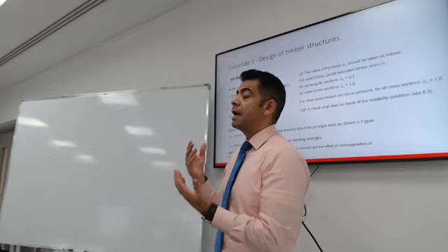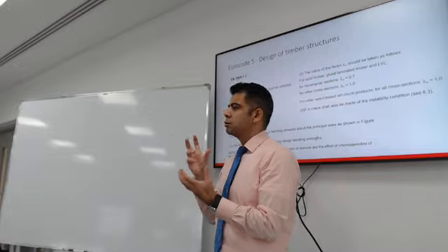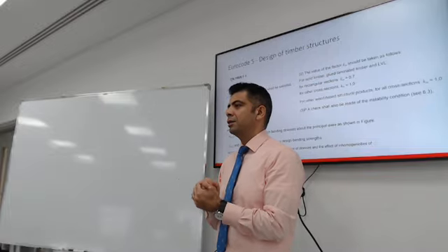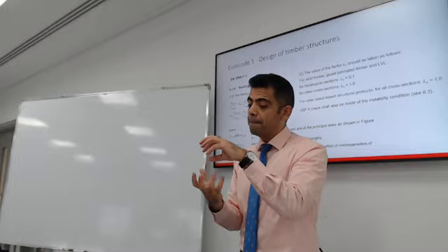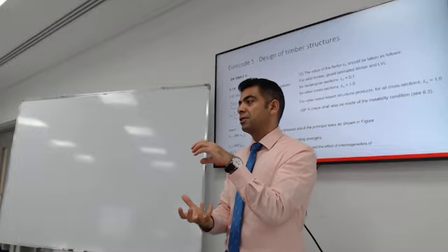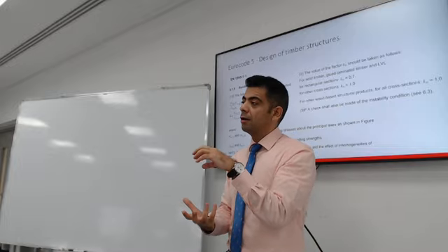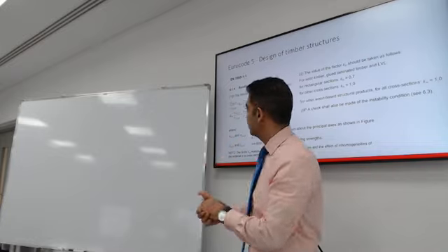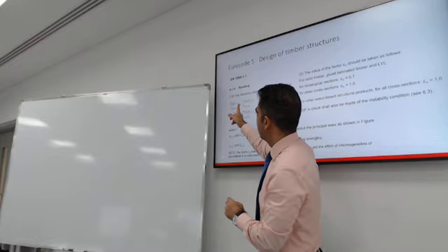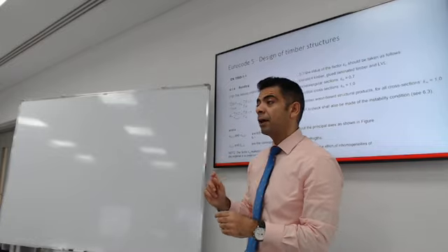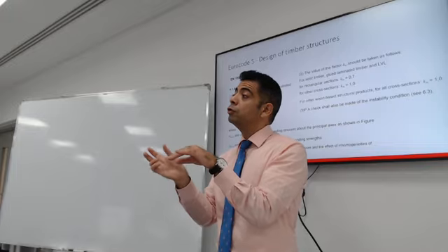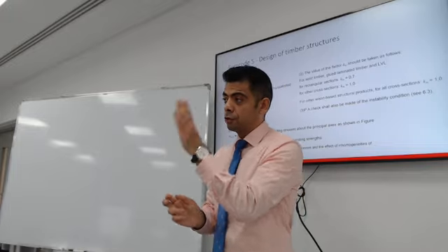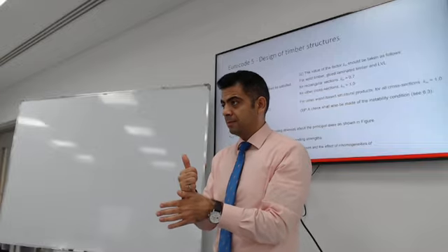Once you have it, it becomes like a simple stress analysis equation. The stress on the section should be less than the maximum stress that the section can handle, or the strength of the section. What about this Km factor? This Km factor takes into account if the moment on the section is in 2 directions, about the strong and the weak axis.